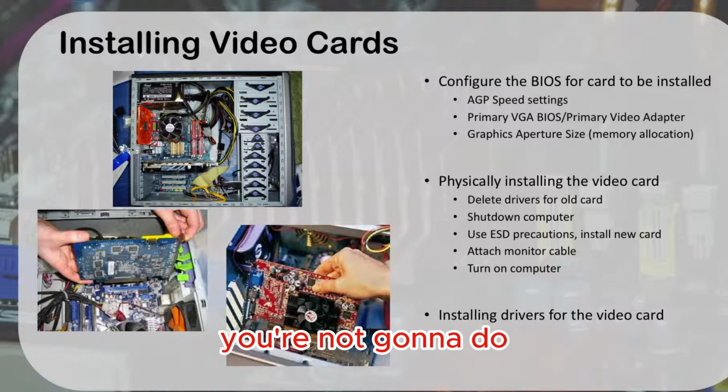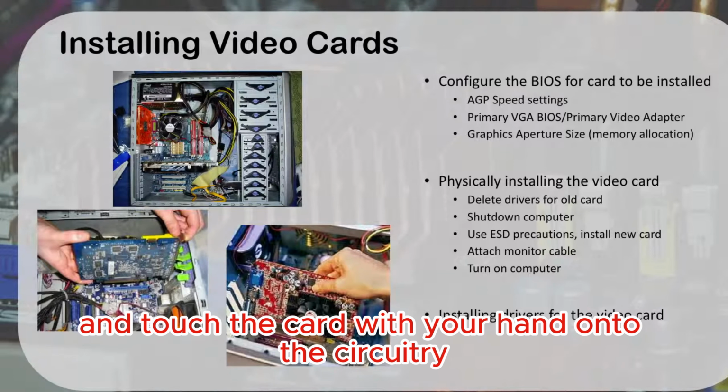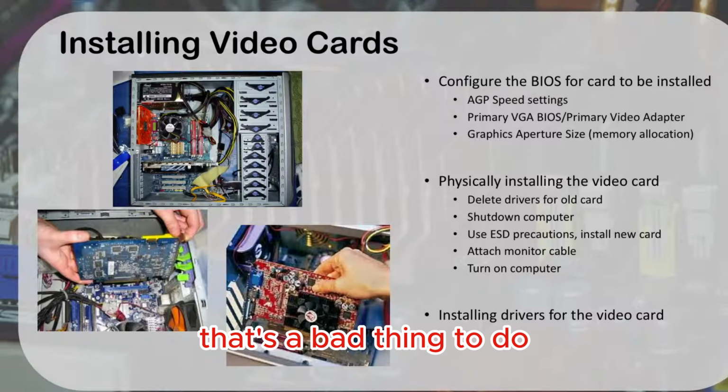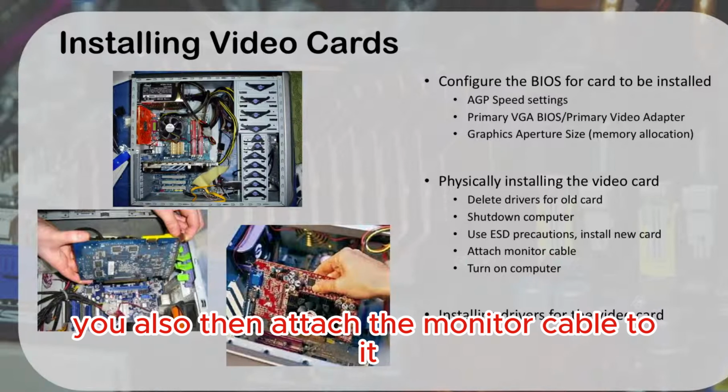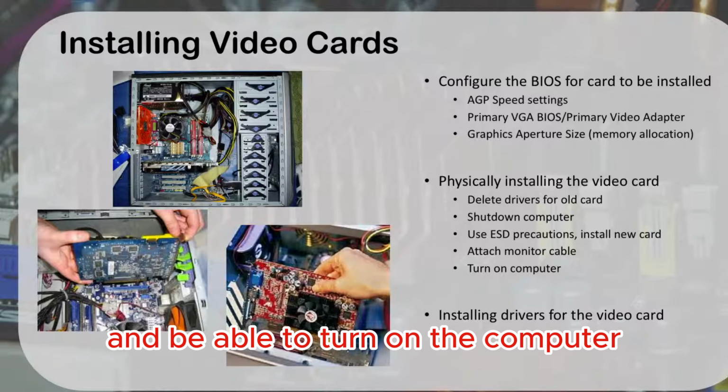You're not going to do like the guy in the bottom right here and touch the card with your hand onto the circuitry. That's a bad thing to do. You want to do it like the one on the left where you're installing it, touching it by the edges. You'll also then attach the monitor cable to it and be able to turn on the computer.